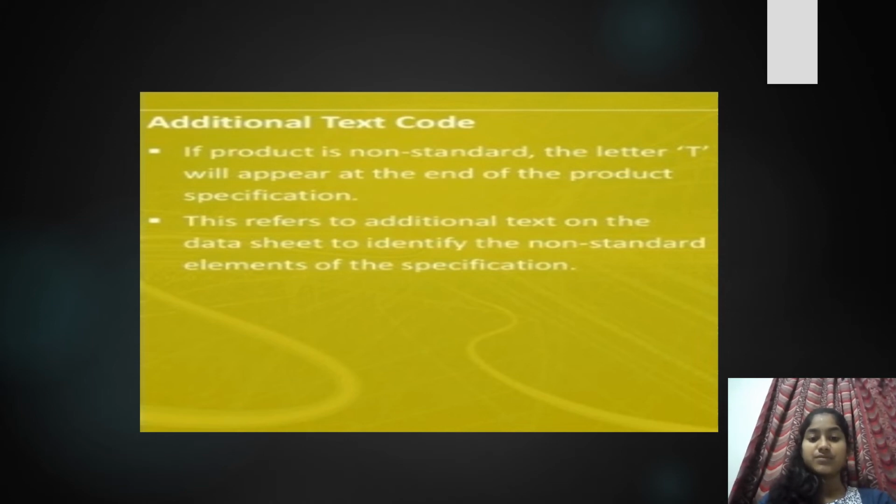Frequency stability. Even though VCXOs are variable, the basic frequency stability still needs to be specified. Generally, this is done for room temperature, 20 degrees centigrade, and with the voltage control point set to the center value. The frequency stability is taken for operation over the operating temperature range. The value is specified in terms of parts per million, ppm. Standard stability specifications are typically plus or minus 25 ppm, plus or minus 50 ppm, and plus or minus 100 ppm as discussed before.